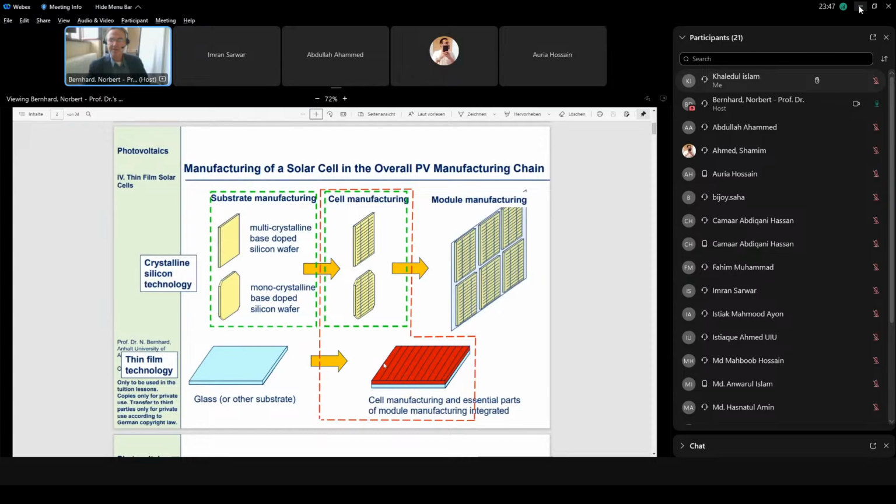silicon. And therefore, of course, these two materials can use a different part of the spectrum, or the electromagnetic spectrum. That means this is a principal concept of tandem or multi-junction cells, that we start with the highest band gap for the top cell and then stepwise decrease the band gaps.